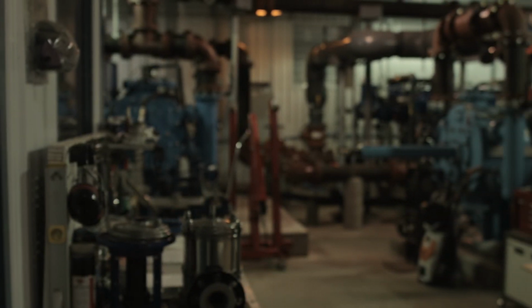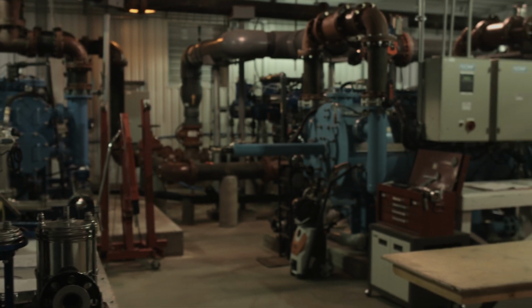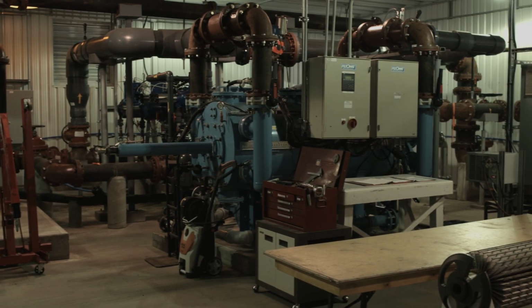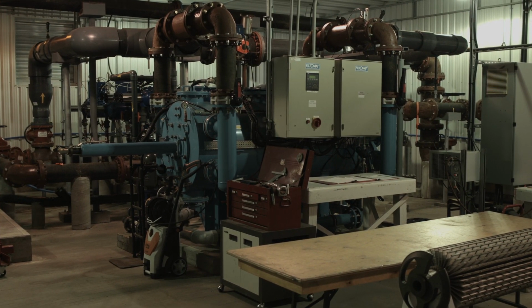Each type of flow meter will have specific installation requirements. Flow meters require undisturbed flow upstream and downstream of the meter. The length of straight pipe required will be specific to the type of flow meter. Also, some types of flow meters need a minimum amount of flow in order for them to function. Therefore, it is very important that the distribution system characteristics are considered when choosing the type of flow meter to be installed. There are two main ways for an operator to monitor and record flow data.